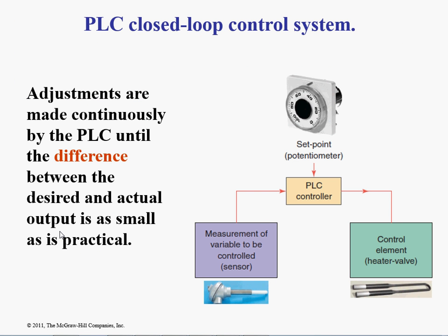So what about an on-off system? What if this is monitoring the temperature of a tank of water with a limit instruction? When it becomes over temp, I open up a valve and dump cold water in there until it falls below temp to the right range, and I shut the water off. And I'm filling it with hot water. So the water cools off, I fill it with hot water until it reaches its limit, and then I turn it off, and I repeat. That's on-off proportional control. That makes sense? And I can do that with limit, greater than or equal to instructions, whatever you want to do.